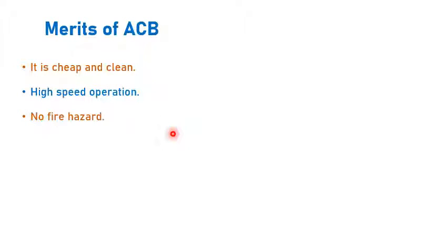And if you see the merits of air circuit breakers, it is cheap and clean, because normal air is used for quenching the arc. And air blast circuit breakers provide high speed operation, and there is no fire hazard possible here because only normal atmospheric air is used as a quenching medium.